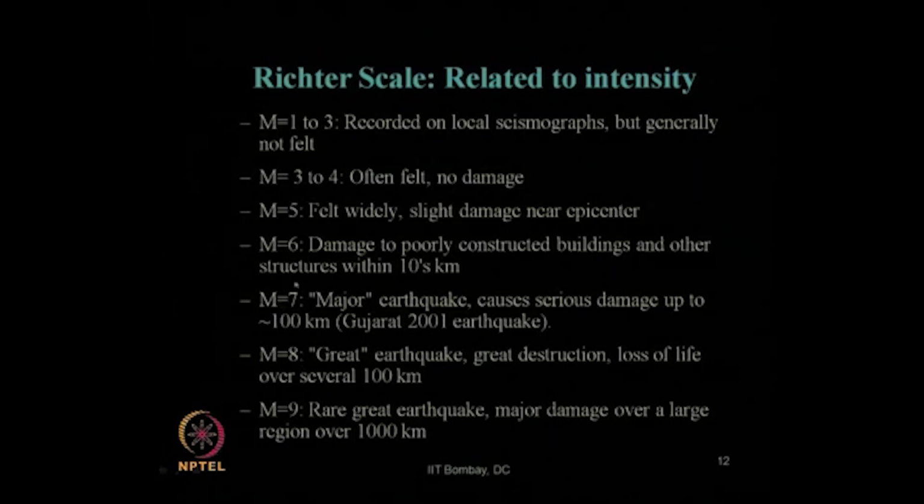Magnitude 8 on the Richter scale or local scale is called a great earthquake. There will be great destruction and loss of life over several hundreds of kilometers. And Richter magnitude 9 is a rare great earthquake, with major damage over a large region, over 1000 kilometers of distance. So, those are the various scales of Richter magnitude and their correlations to the damage to structures and how observers feel it.